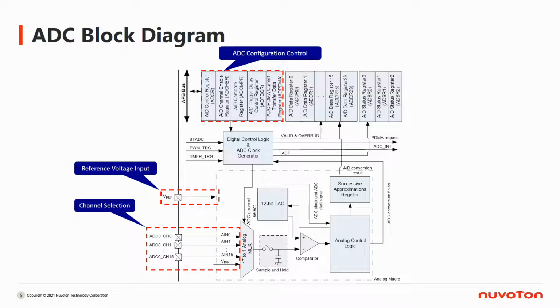When we want to measure voltage from an ADC channel, like from ADC channel 0, the switch in sample and hold will be turned on, and channel 0 will start to charge the capacitor. When it has been charged for a period, the switch will be turned off. Then the voltage in the capacitor would be the input voltage. The input voltage then will be measured by the successive approximation register ADC in the way we have mentioned before and stored in the corresponding register.